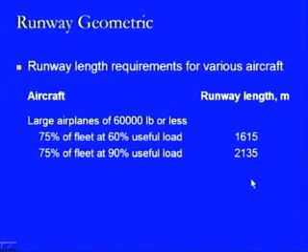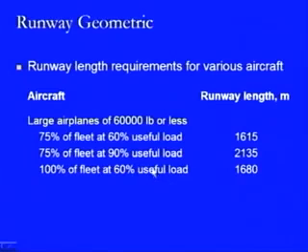Whereas if the useful load increases to 90%, then this will be 2135 meters. Further, if we increase the fleet size from 75% to 100% and keep the useful load at 60%, then the runway length will increase from 1615 meters to 1680 meters.